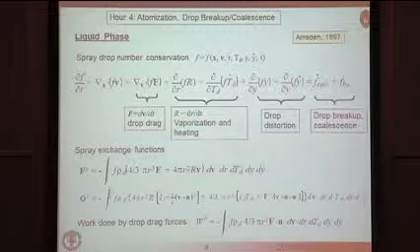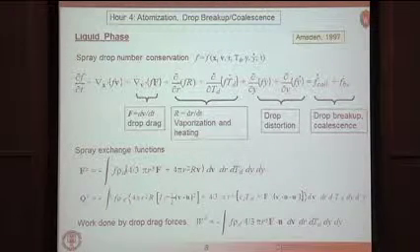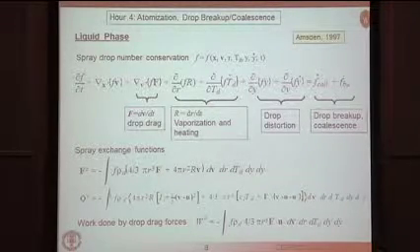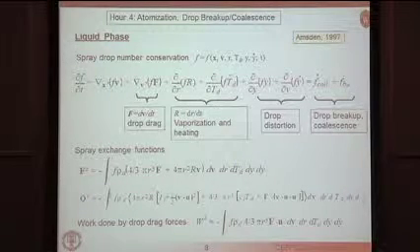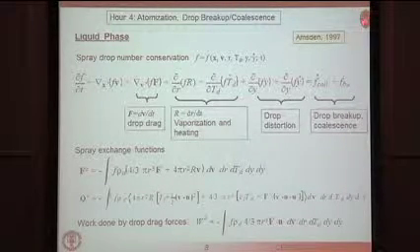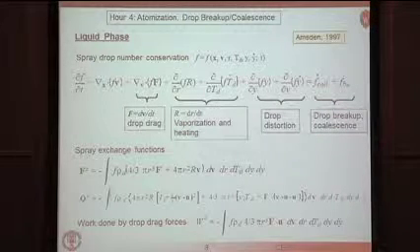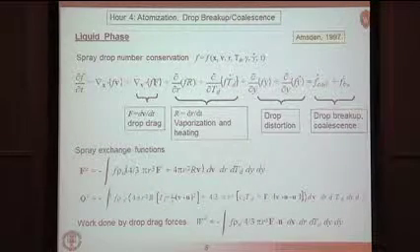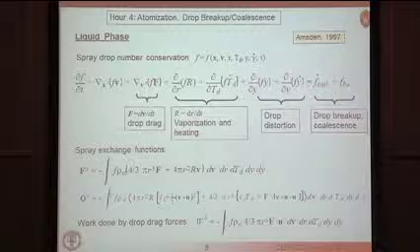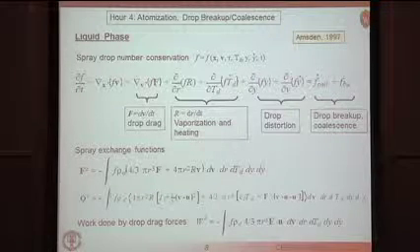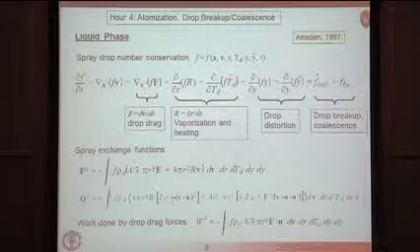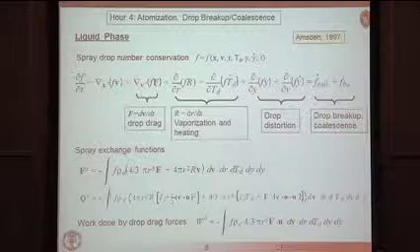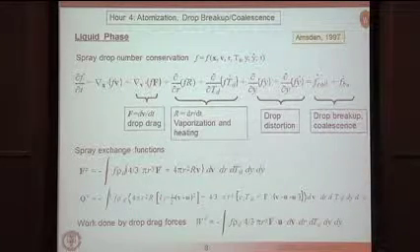And you saw now we have the source terms, R for rate of radius change, F for the droplet drag terms, and then we have the heat transfer. So now looking at the liquid phase, and again, all of this is described for example, in the Kiva manuals. Here's our distribution function. I've just added a couple more independent variables here. Y, you'll see later, is a measure of the distortion of a droplet from being a sphere. And Y dot is the rate of distortion of the droplet. We'll see that distortion of the droplet changes its drag coefficient.